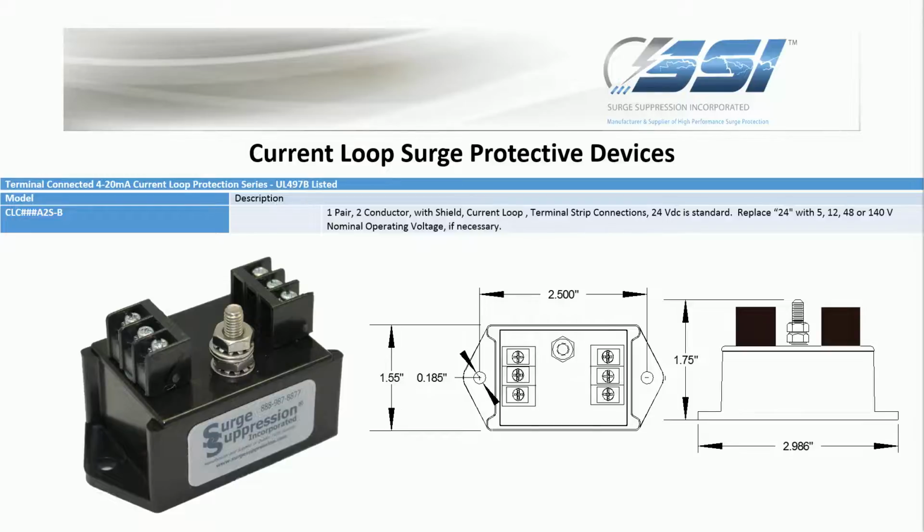This avoids creating a grounding path between the monitoring equipment and the sensor assembly if there is a difference in ground potential between the equipment at both ends of the circuit, and helps to ensure that any difference is addressed solely by the power ground that goes back to the main service entrance single-point ground source.